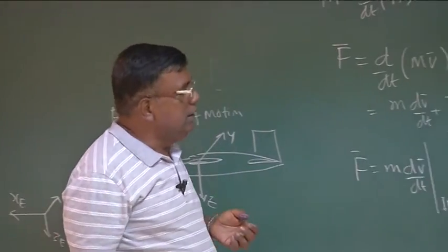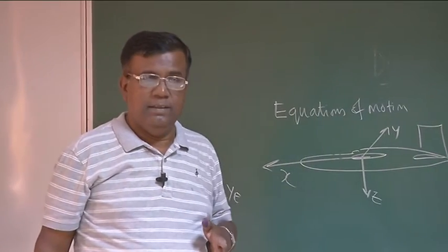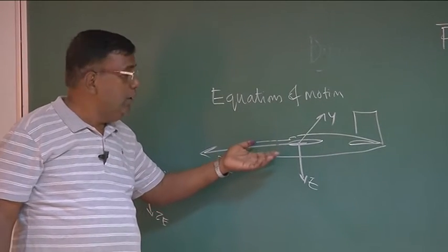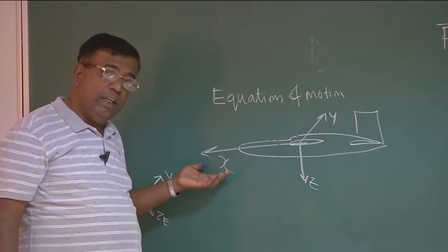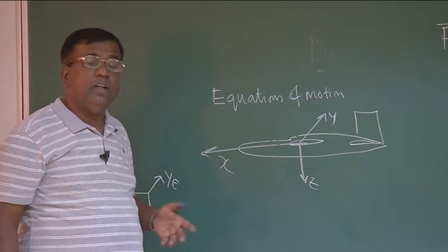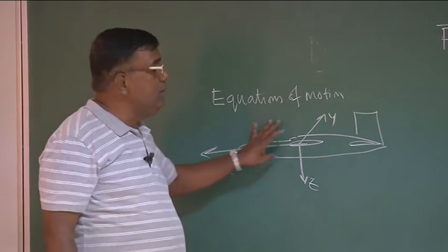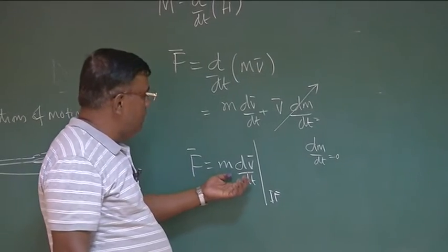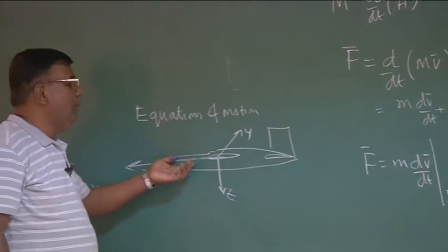The second thing we realize is that the aerodynamic forces depend upon the relative airspeed. So from that angle, the body fixed frame will be very, very important. The speed of the aircraft with respect to the atmosphere, relative to wind, will be very, very useful, because aerodynamic forces depend upon relative air velocity. So we had a motivation to work in the body frame for these two reasons. But how to do that? We need to work in an inertial frame, but we have a motivation to work in the body fixed frame.